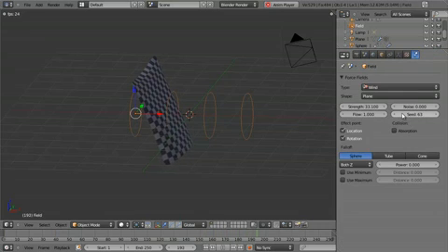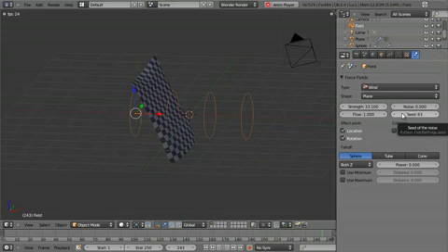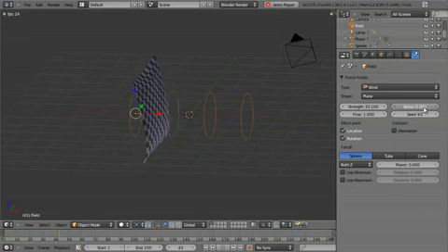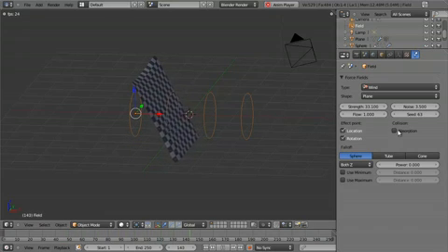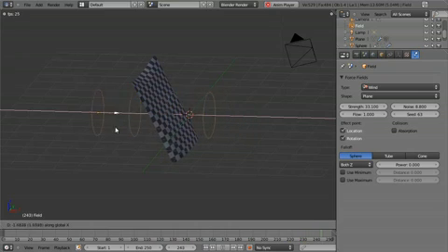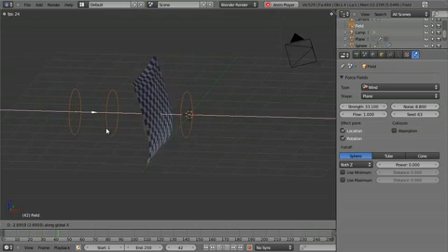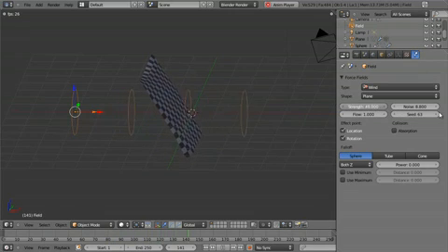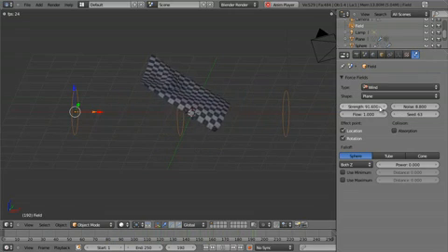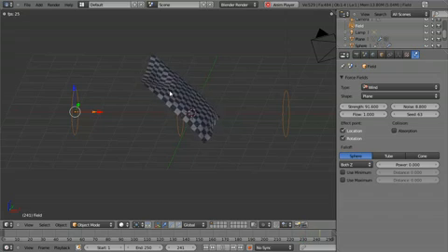And we have a simple wind, but it's kind of boring. Wind doesn't normally blow with a solid force, unless it's, say, a fan. So let's add some noise to this. Now the wind will go in and out of strength so that there's some variation. We can increase this a lot more, maybe move it back along the x-axis a little bit more. We can increase the strength even more if we want, taking it all the way up until you can see it just blowing through there.